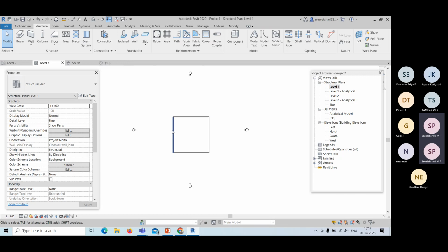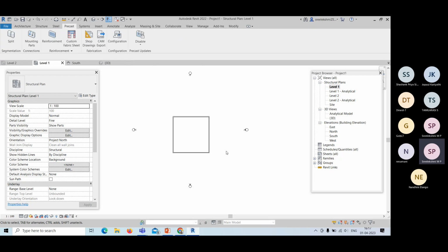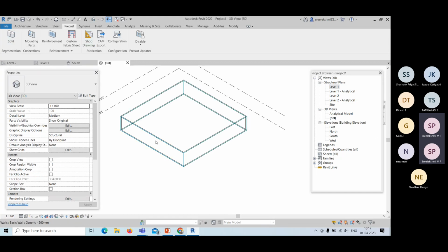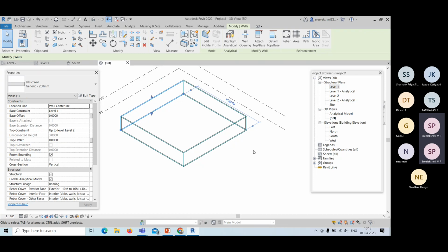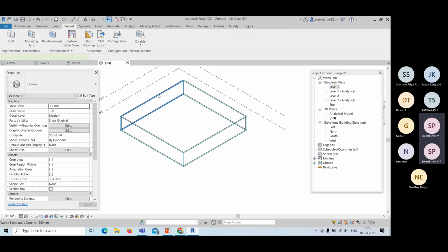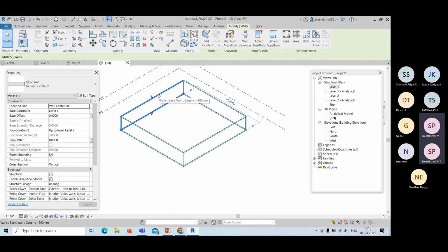So I can go to Level 1. First of all, we have to do an action. Suppose I want to perform a specific action now, but before that, we have to do a split. Only after we split the walls, or even if it is a slab, can we access the changes. So we have to do splits in between. Now it's just a single wall, and its length is about 15.8 meters. It's not possible to cast such a large length wall.